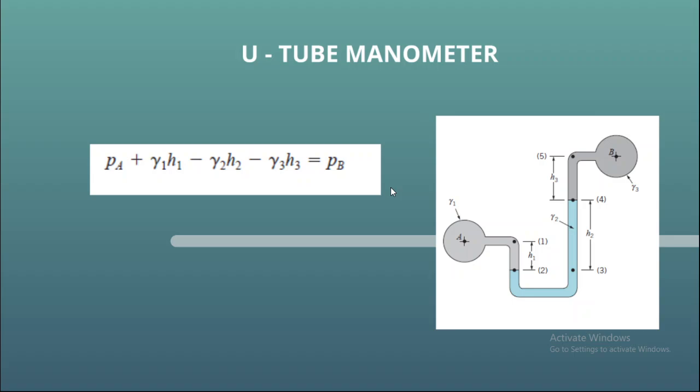In this numerical, the U-tube is connected with a closed tank in which water is filled partially, and there is a space available. The other part is connected with air which has a pressure of 16 psi absolute, and at the upper part the valve is closed. If you start to calculate the pressures, you get the pressure with reference to absolute.